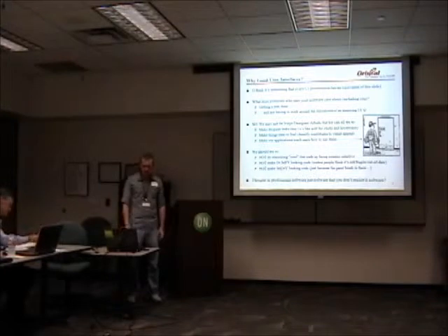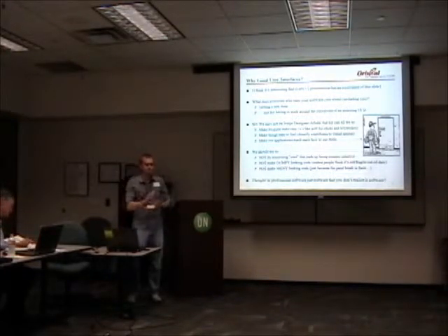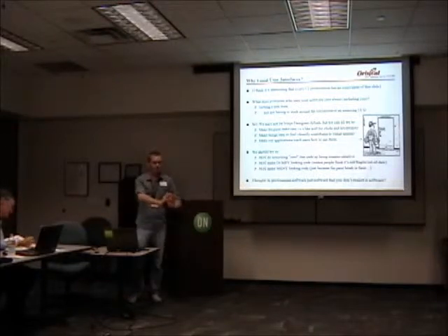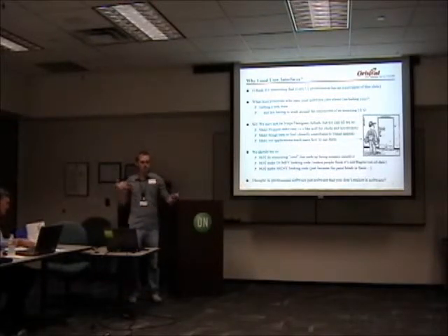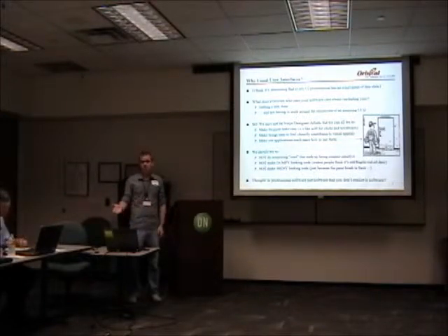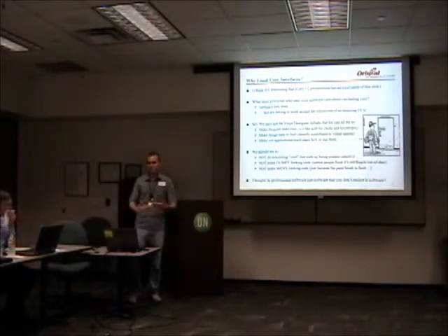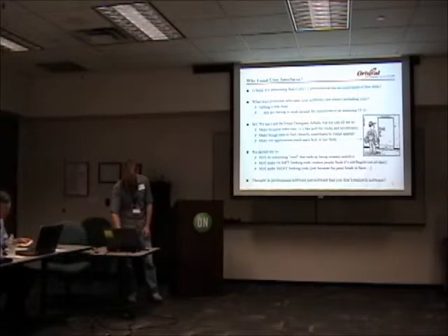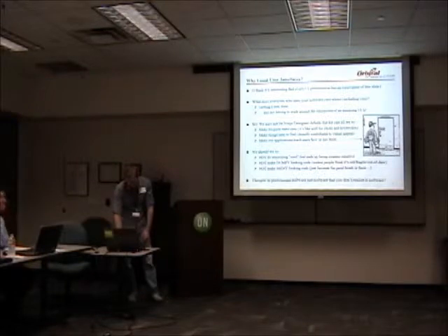And we should try to avoid that cool new feature in LabVIEW that we want to shoehorn into our application that then becomes non-intuitive to the user. And I fall prey to this all the time. One of the demos I brought today is something that I designed 3 or 4 years ago, and I broke that rule. I'm reviewing my own designs, and I wish I hadn't done it. We don't want to write purple code, as Jason said, just because the paintbrush is there.